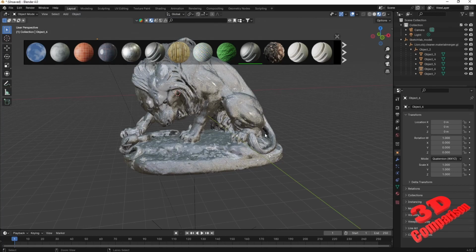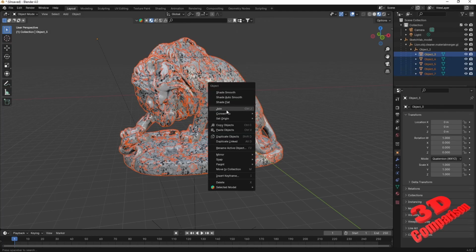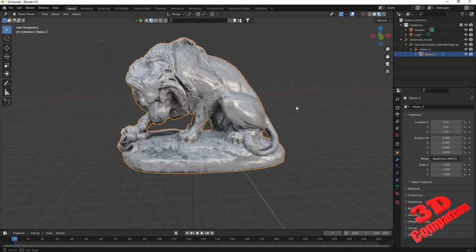So therefore, in order to have a uniform texture for this, I will just select everything, and I will go over here to join. And now, if I will just apply the same texture again, because I pressed Ctrl Z several times to go back, over here, if the Blender Kit will not pop up automatically, you can just do a search. And we're gonna see for gold material, for example, we're gonna have 600 results, but sometimes you need to go back and forth between those.